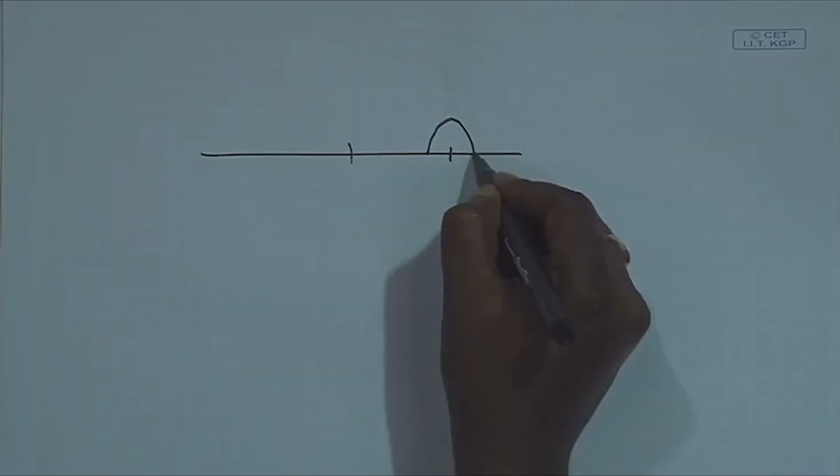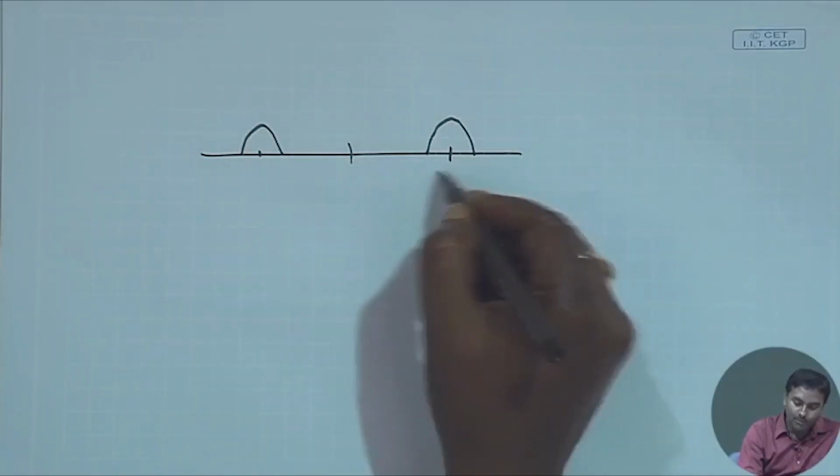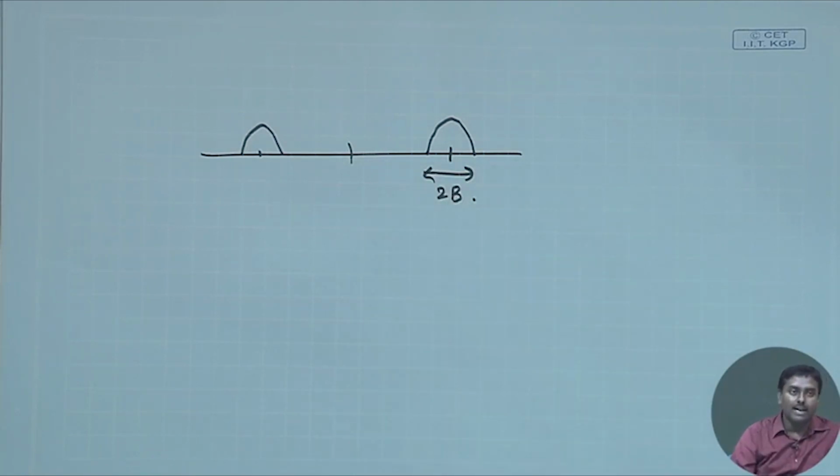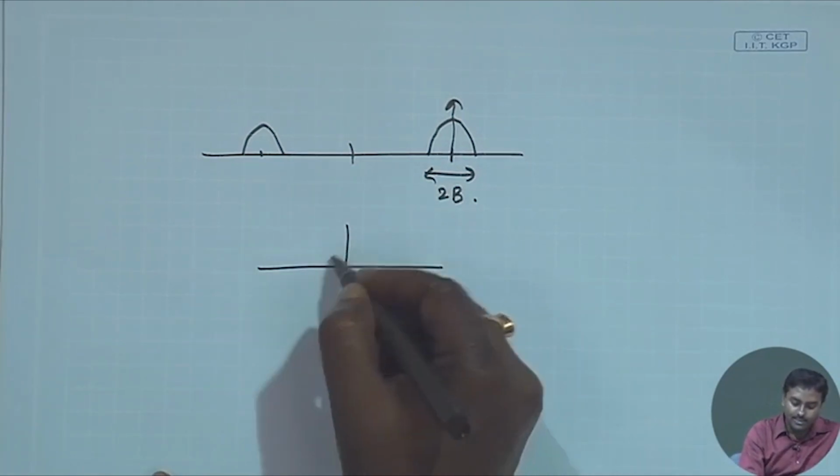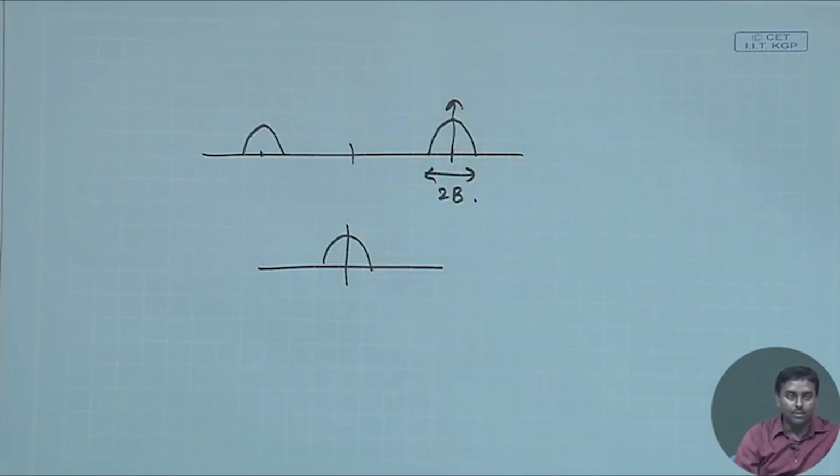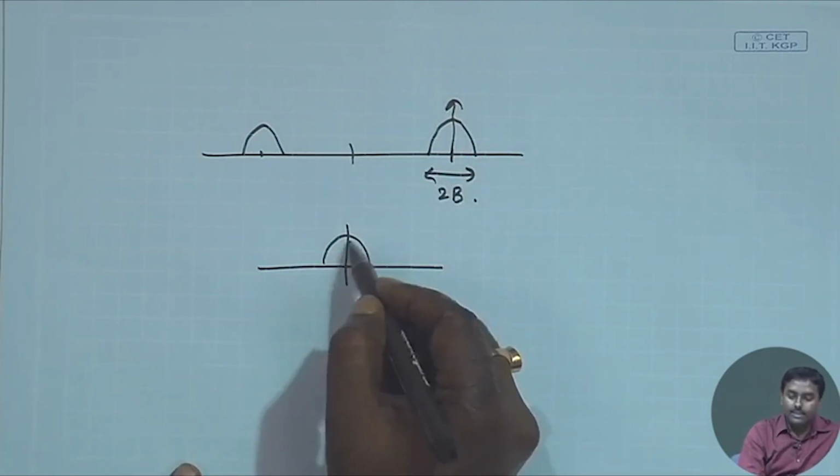Okay. So, in the last class we have already discussed the advantages and disadvantages of AM and DSBSC. But in both AM and DSBSC, if you see how it occupies the spectrum, whether it is suppressed carrier or not, it will be occupying this entire 2B band. If I put the carrier on top of this, nothing else changes, at least in the frequency domain, still it occupies 2B. But I can see already, the message signal which is getting translated over here and creating this 2B band is even symmetric, right.